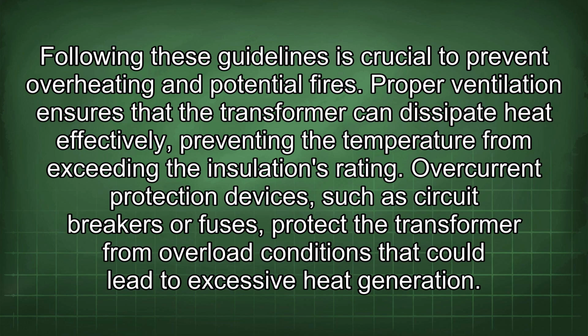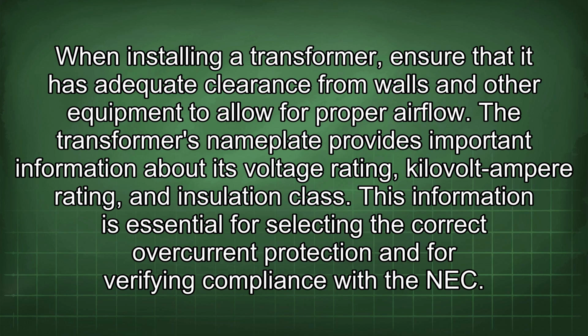When installing a transformer, ensure that it has adequate clearance from walls and other equipment to allow for proper airflow. The transformer's nameplate provides important information about its voltage rating, kilovolt-ampere rating, and insulation class. This information is essential for selecting the correct overcurrent protection and for verifying compliance with the NEC.